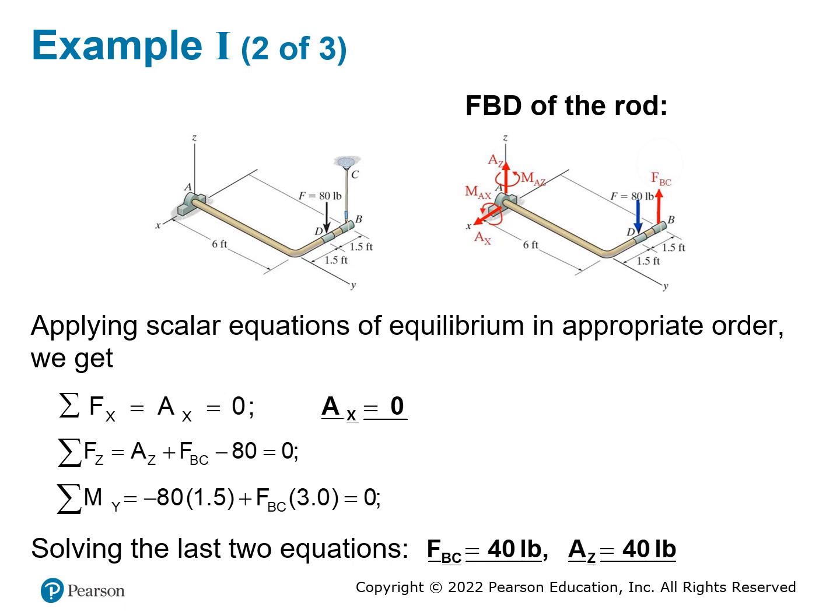So this is a bearing, but we only have a single bearing, right? When you have a single bearing, you not only have the reaction force, you also have a reactive moment as well, which we talked about in the previous few slides. Unless you have two bearings or more, then you don't need to worry about this reactive moment. But over here, we only have a single bearing, so you have to consider those as well.